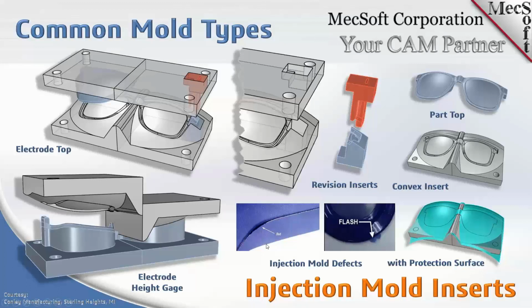And then on the left shows a mismatch in the parting line. Now the mismatch can occur if your tolerances aren't tight enough, if your setup is not correct, things of that nature. So on the right, we have the flash, which is caused by degrading of the parting line. And on the left, we have mismatch, which can be caused by incorrect setup or incorrect tolerances. So let's move directly above that.